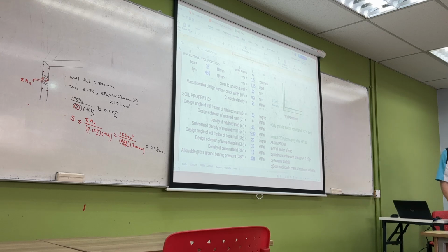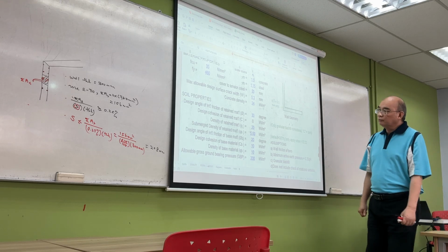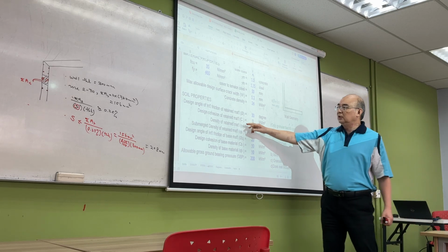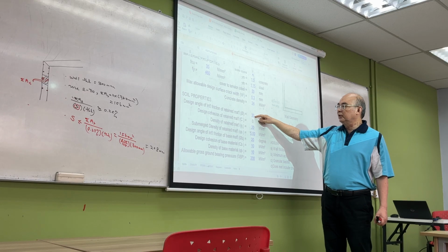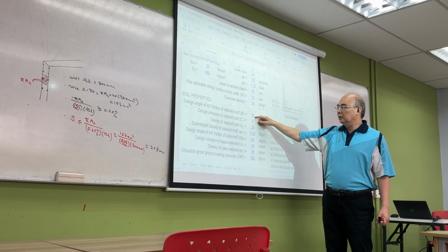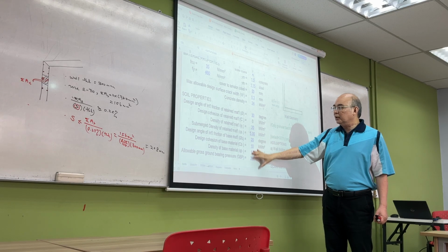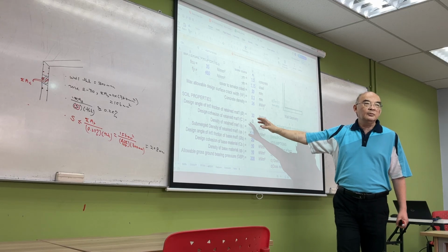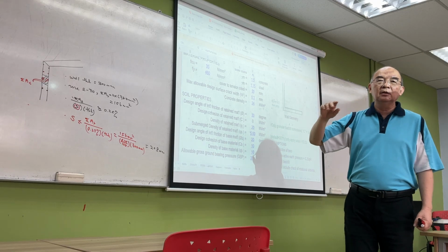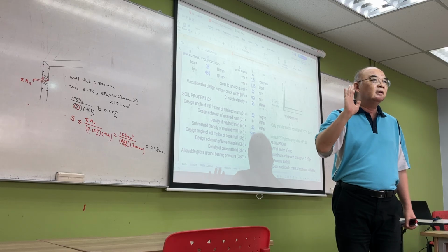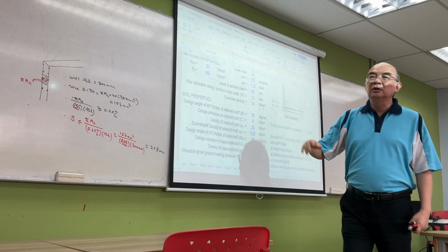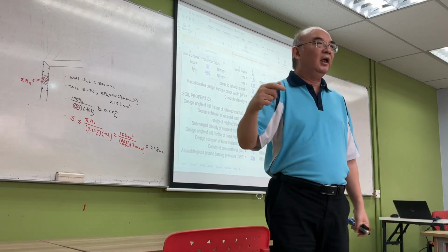Over here, of course, they calculate, for example, the design angle of internal friction 30 degrees, okay, and so forth. So this actually helps you calculate the Ka, the active soil pressure coefficient. Okay, in a test I'll tell you what Ka is.